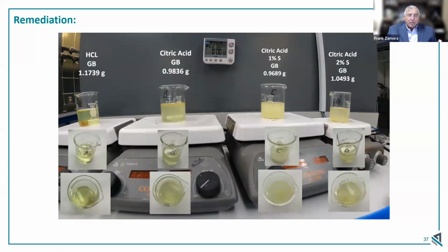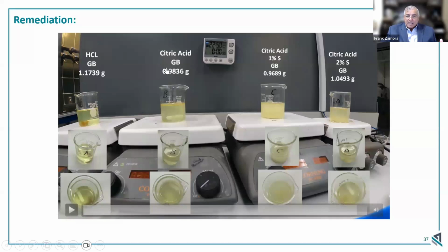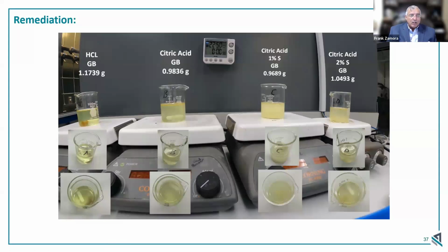Now, the beauty of citric acid versus hydrochloric acid is if you were to run hydrochloric or acetic acid, those are a little stronger. Although the strongest is the hydrochloric acid, you're going to release more fines. So if you have a carbonate formation, you're going to release a tremendous amount of fines and create a bigger problem, because now your gummy bear hasn't gone away, it's dehydrated, and you're adding additional fines to it. So you might possibly even plug up the well.